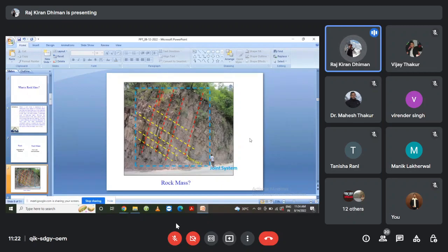There are also other factors, because I mentioned in the beginning that there are discontinuity planes. A discontinuity plane is like a crack in an object. There is a crack, and the movement can be along that crack, right? So we have to classify what the factors are which will govern this movement along the planes. This is one of the very important parameters of rock mass classification.